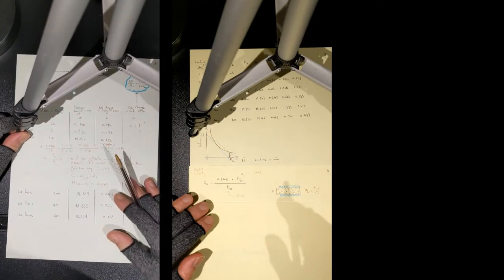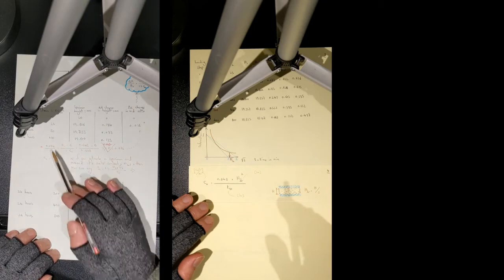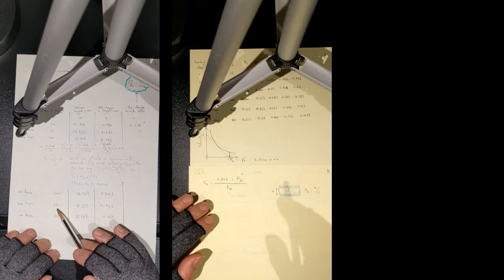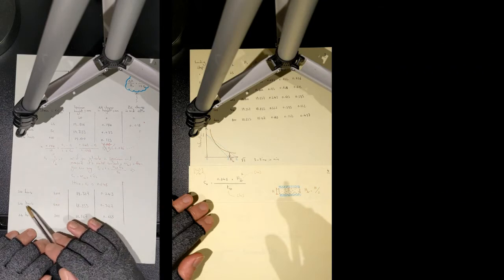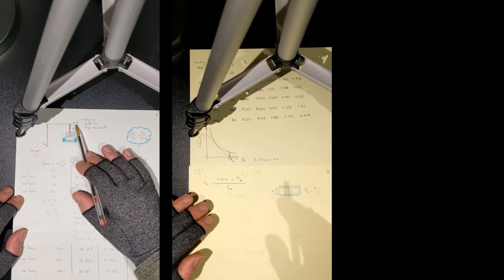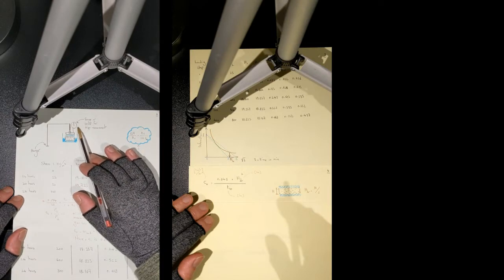So look at here, I have then gone up from 100 kPa to 200 kPa, 24 hours, 400 kPa, 24 hours, 800 kPa, 24 hours, and I've registered all the delta H values, which are measured by using a digital dial gauge, LVDT, or a mechanical dial gauge. And this is really the raw test results which comes from an oedometer test.